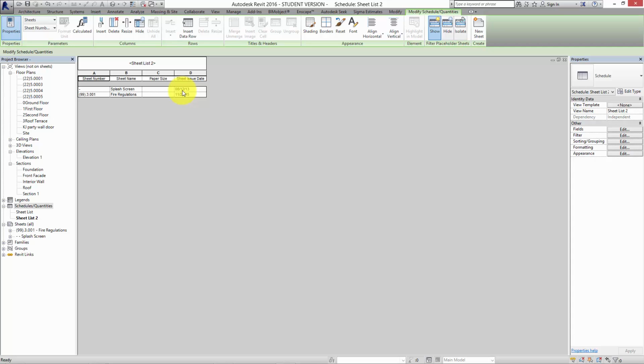It is a good idea to write a sheet list up, because sometimes if you sit down with your group and try and figure out what drawings we need to have in order to explain the building, you actually then realize how much work you need to do, and where the model is lacking and so forth. So it's actually a good procedural exercise as well.